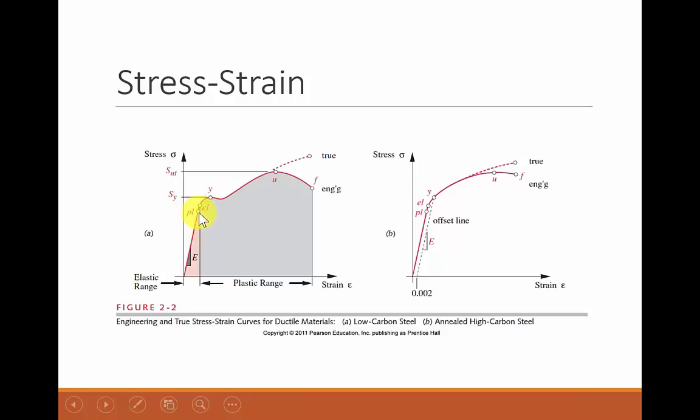If I continue on, and very often the plastic line and the elastic line are at the same place, so this is kind of no man's land in between there. A lot of materials, these are exactly the same point, or so close to the same point we consider them the same point. When I get beyond into the plastic region, notice for increasing the stress, it's beginning to strain faster, all the way into the point where I hit some sort of yield strength. And this is what's really important. This is what's going to determine whether this part is going to fail. If we put so much stress on it that it begins to yield, we're in danger of it breaking. Okay?